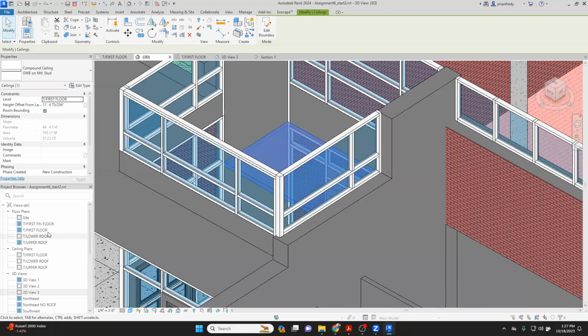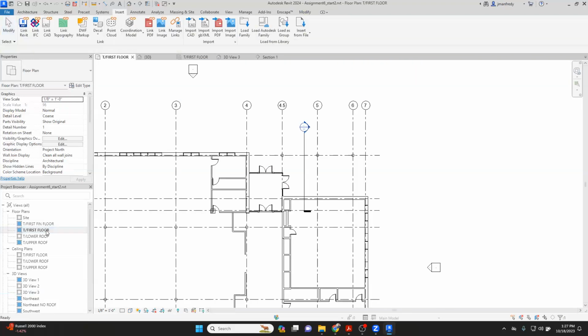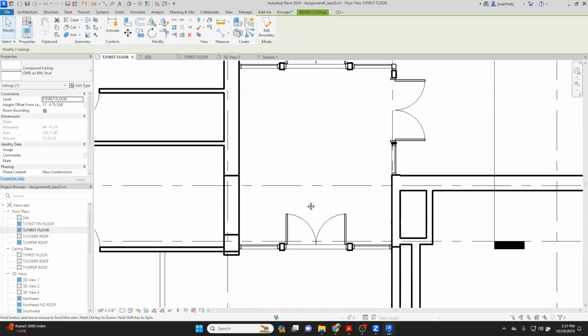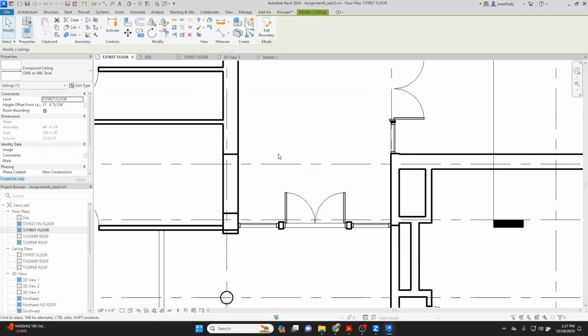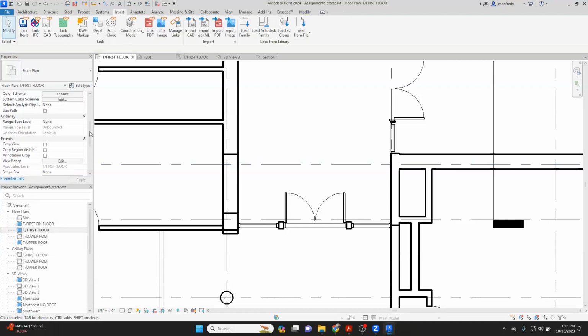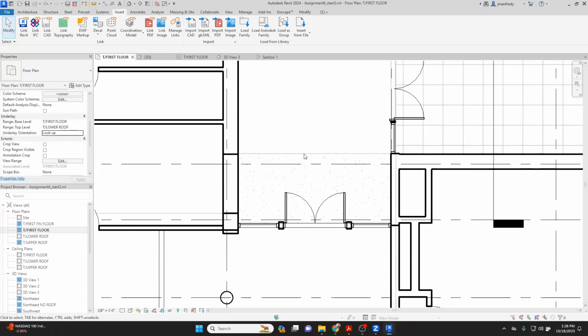So if I were to very quickly draft it, here I'm on the floor plan, I can't see the ceiling. I'm drawing it here, not in a reflected ceiling plan, because in a reflected ceiling plan, the wall shows up at like 6 inches tall, and you're not going to see it up here. So on the floor plan, I'm going to show the ceiling. I'm going to go from the first floor looking up to the second floor, hit apply. There's the wall right there.